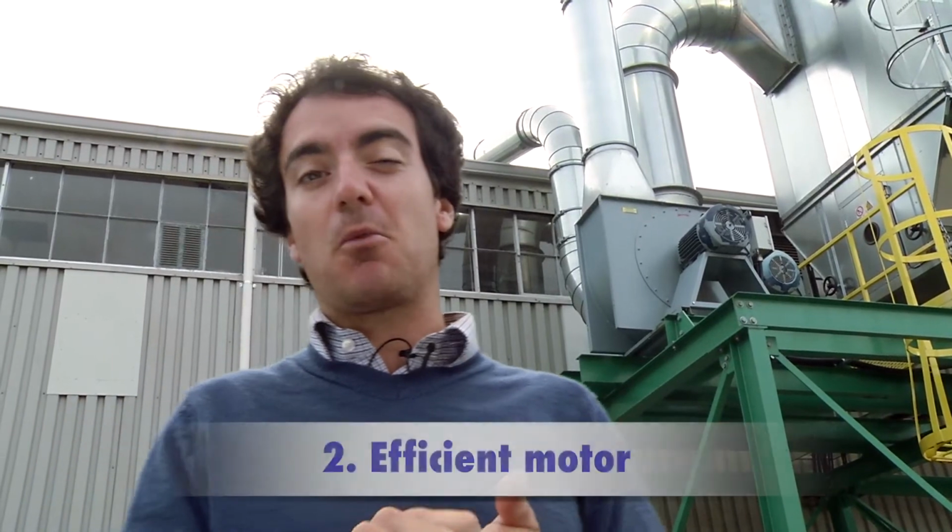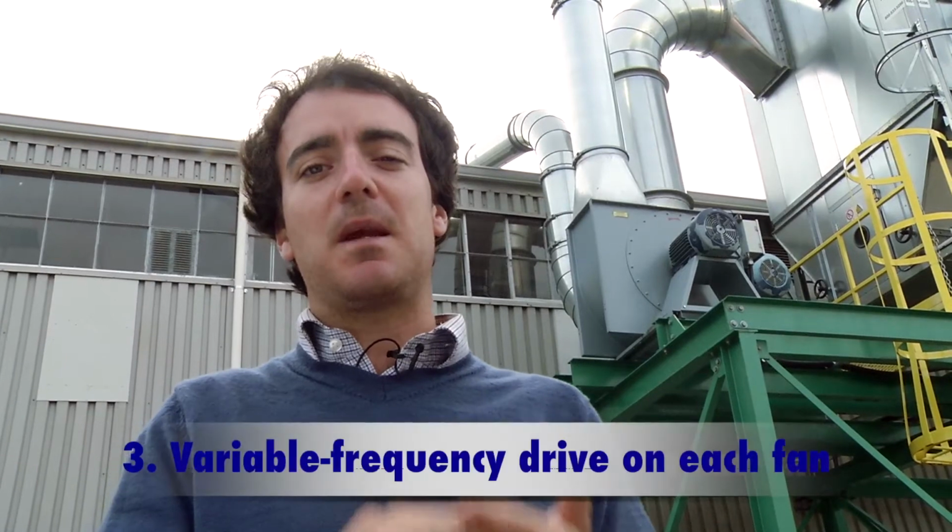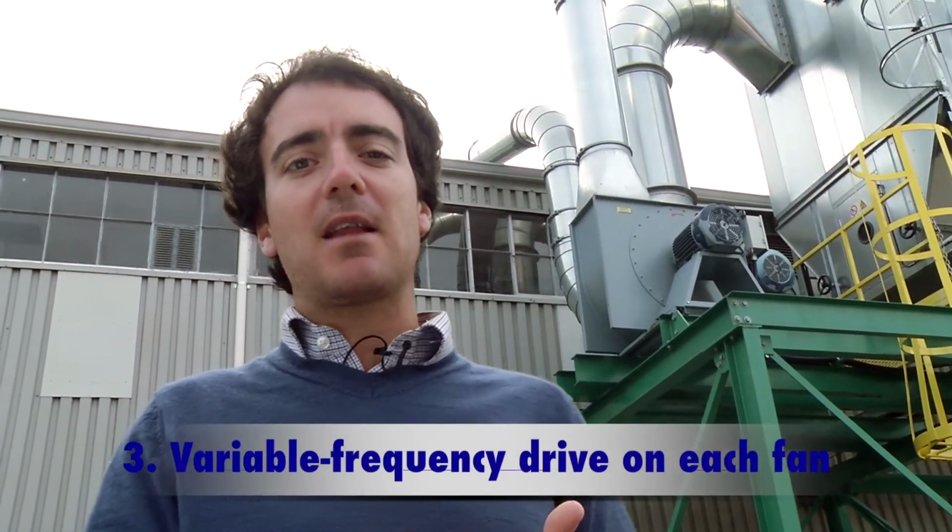The other idea is that you want to make sure you have an efficient motor. In this case, we have high efficiency ratings for these motors. And the third thing is you want the fans to rotate at the speed that you need. And for that, we decided to go with a combination of 2 variable frequency drives that are helping the system adapt to the true need. And again, I'm going to tell you a little bit more about that when we go inside.